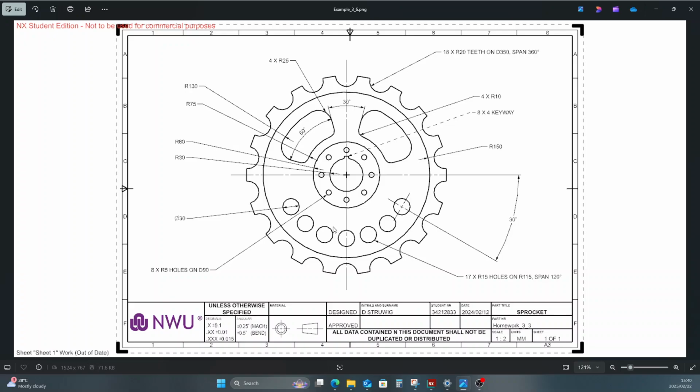It's also important to consider where you start your sketch. From this it's quite clear there's a definite center, which is that point. But for some other sketches there might be no clear center point where you should start, and then you should use your own discretion to determine where to start. Typically you look at where you can have some symmetrical features so that you can use the mirror feature. That's how you determine the best point to start a sketch.